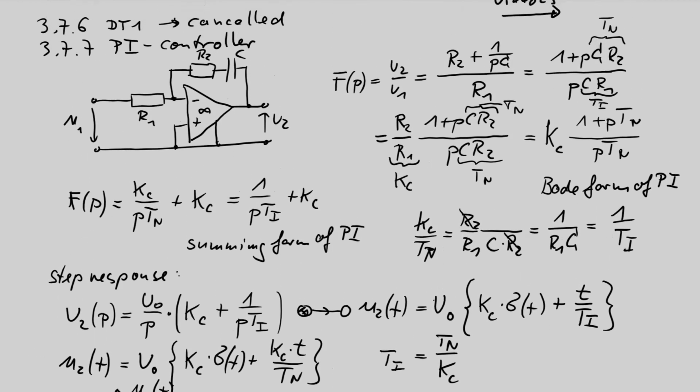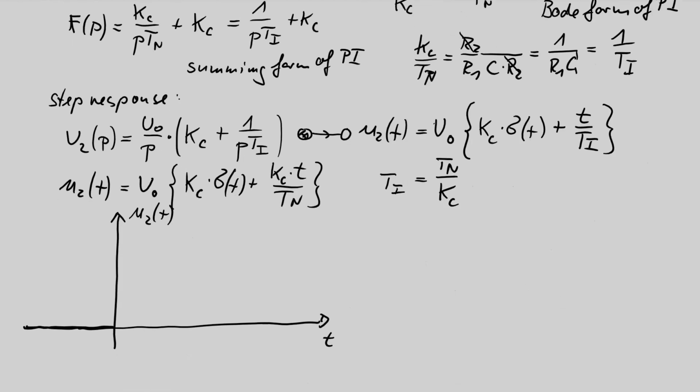Note that if you measure the step response, first you have to unload the capacitor C to reach these initial conditions. That you have to force; it does not happen by itself. You have to short circuit the cable connected to the capacitor and unload it. Then you get 0 starting voltage.